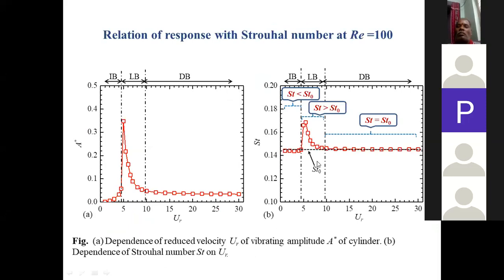Now, when you are working on this vibrating cylinder, in this synchronization branch, in the initial and lower branch, with the change in frequency, the frequency changes from the stationary value in both the initial and lower branch. But in the desynchronization region, there is no change in the frequency. It is the same as that of the stationary cylinder.